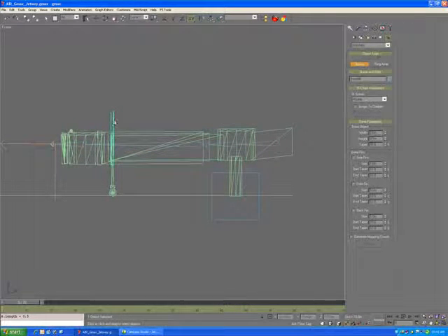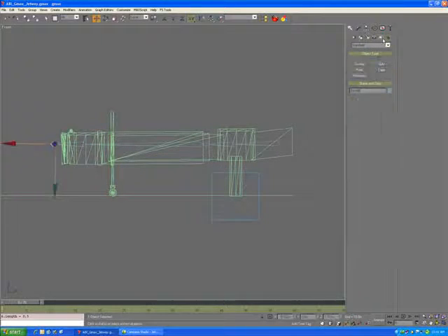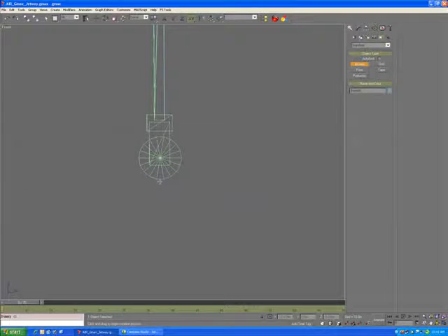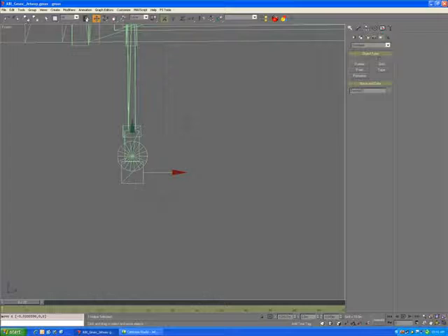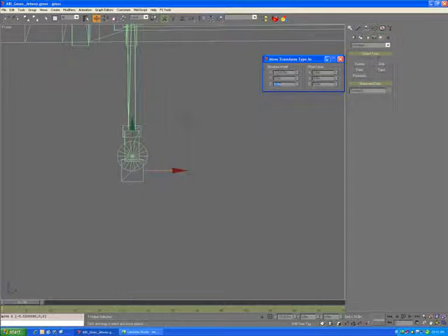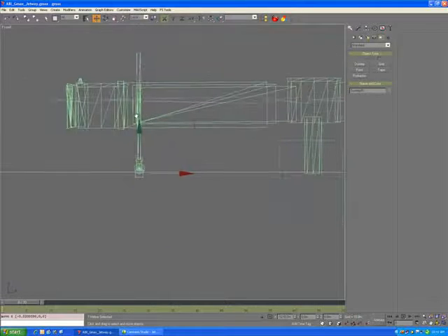And now I want to create one for the legs of the Jetway. Actually, before I do that, I'm going to turn off the snap toggle and create a dummy down here at the base of the Jetway. I'm going to set its position to be 0, and this will be used to create the IK handle that locks the wheels to the ground.